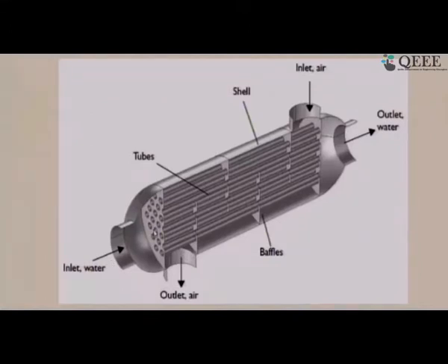Energy transfer is taking place from one fluid to the wall of the tube. Then there is conduction through the walls of the tubes, and finally that energy is transported to the fluid which is outside the tubes. So we have convection heat transfer on the outside, which is flow over a tube, and convection heat transfer inside, which is flow inside the tube. So we have two different types of situations for which we need to know how to estimate this heat transfer.